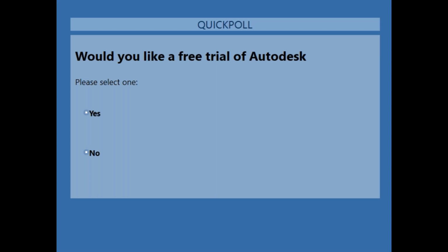All right. I am trying to dig through a lot of these questions here. One of the questions is, can more than one person work on a project at a time? Absolutely. So one of the huge benefits of Autodesk Takeoff is that it is a cloud-based program, and so that enables a lot of different team members to jump in, work off the same plan sets, and how we would organize those takeoffs by those different team members when they're collaborating together on a project is based off of those different packages. So sometimes, as a best practice, some customers might create an architectural package and put their initials on the end of it, but it allows different team members to be able to see the different takeoffs that their team members are doing and continue to work with the same plan set. So not everyone has to download the files onto their desktop to get them set up themselves for their own takeoffs. Everyone can collaborate on the same plan set.